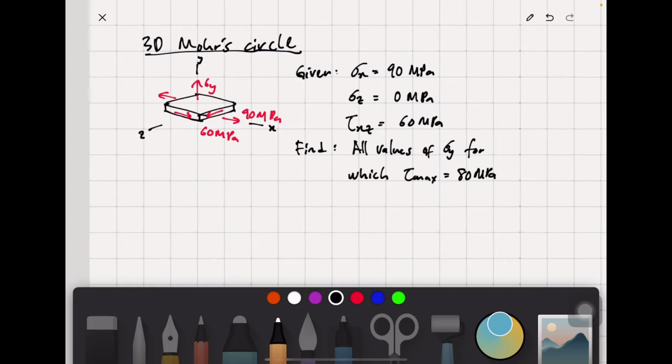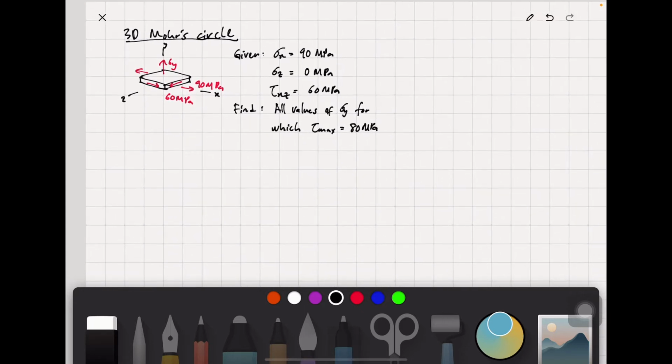First of all, you're going to recognize the stresses given, list them down, establish their coordinate system, and go ahead and draw, and of course to draw a circle we need two points. For this example, we can pretty much predict that the formula will be useful, because we are not going to use graph paper. Even though for this example I created the drawing on graph paper, you can have a look at the exact drawing for the circles.